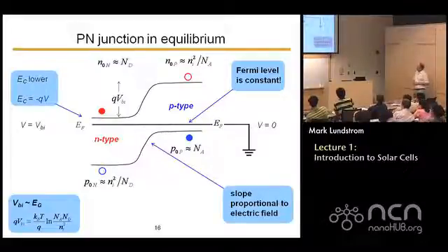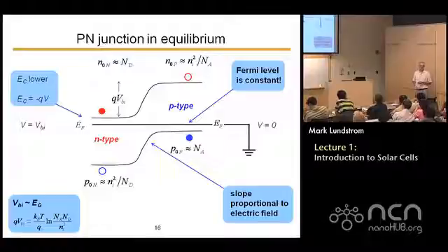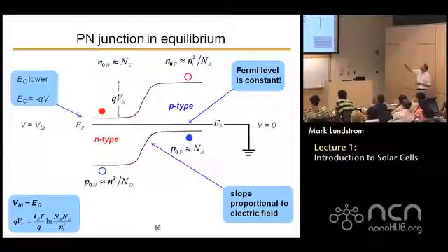Okay. And one of the other things that we teach students in beginning semiconductor courses is that the variation of that energy band is occurring because there's a variation in the local electrostatic potential. So the slope of that is the gradient of the electrostatic potential. It's the electric field. So if you look at the gradient of that, you can get the electric field. You can see it's positive there.